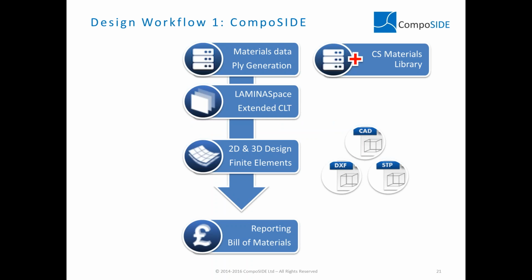So typically, to understand what properties our composite materials have, we need to define the processing type, matrix material, and fiber type. But that's just for plies. We can choose different types of cores from their materials, so balsa, PVC, honeycomb, plastic, the list goes on. Compared to the materials, you can see our geometry is fairly simple.